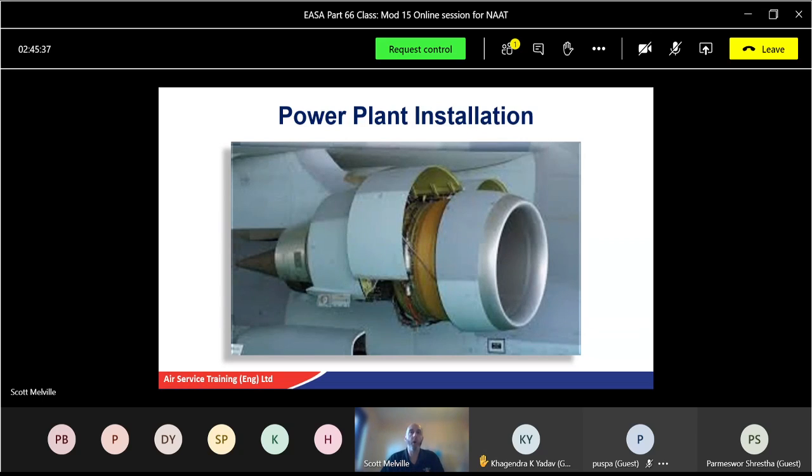So how do we recover static droop? What happens there? We want to go up, so we have to increase the fuel flow rate. What's the name of the system that does that? What do we call that system that's on the collective?